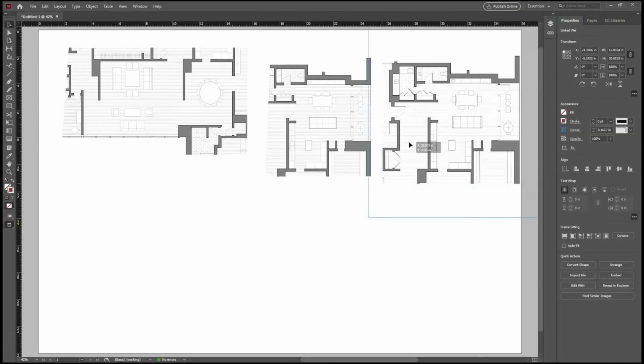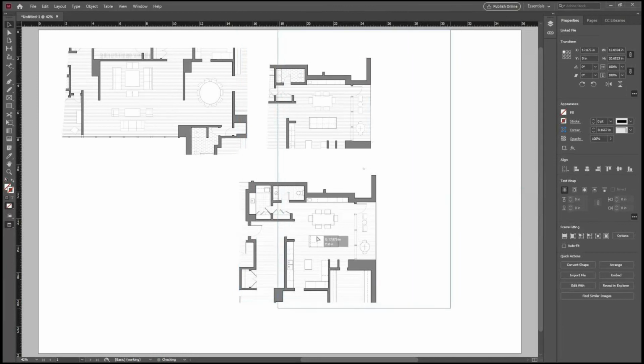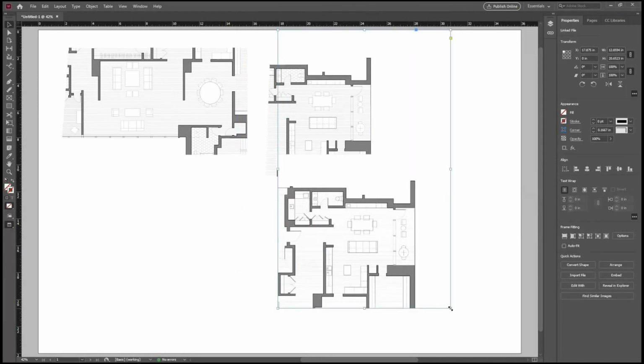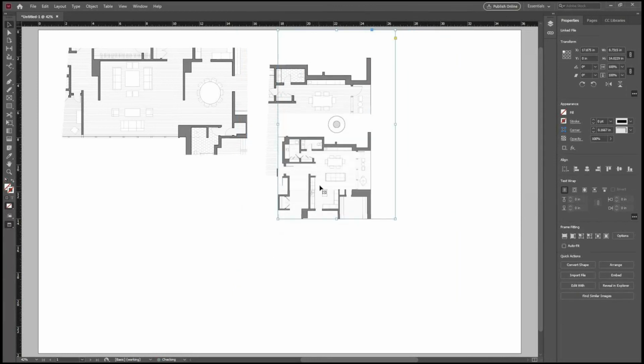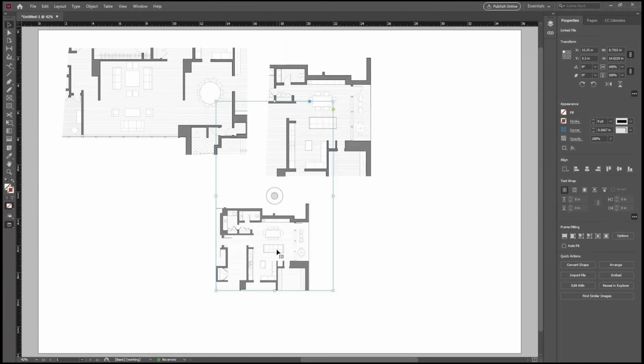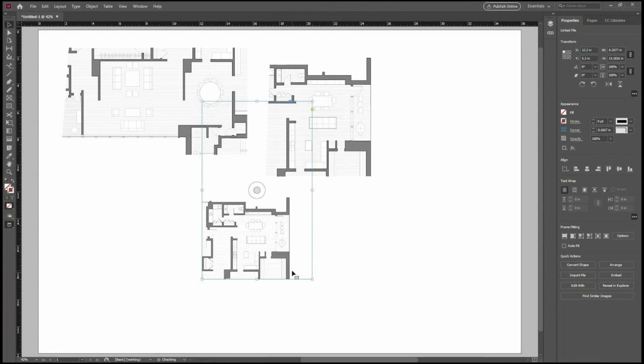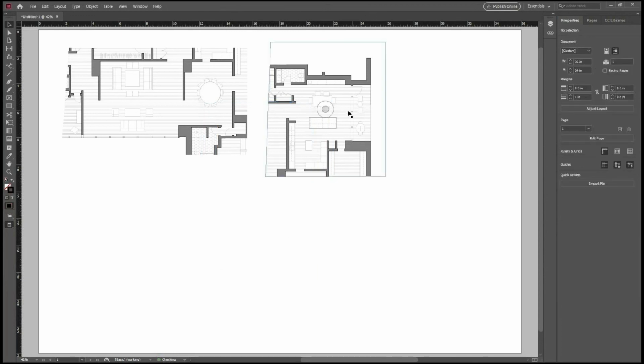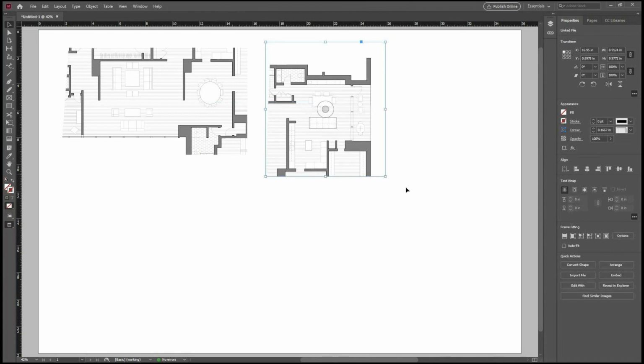The only trick is if you're going to use JPEGs, make sure that you always shrink the file. Never make that file bigger. It actually gets sharper and nicer as it gets smaller, except for hatch patterns like the floor hatch, which you want to avoid.